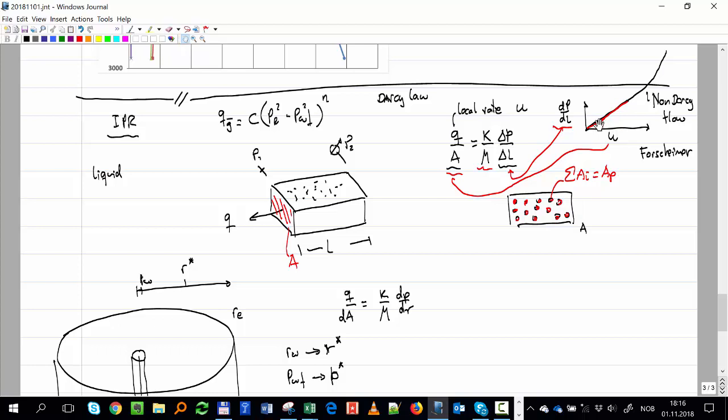And luckily, that's very appropriate for flow of liquids and some gases, some velocities of gas. For high velocities of gas, this is no longer valid and we have to use something else. That's why we have the n in the equation, what I told you the first day, right? This n is between 0.5 and 1. When it's 1, you have this linear regime. When you have 0.5, you are in this regime. And everything else is in between.